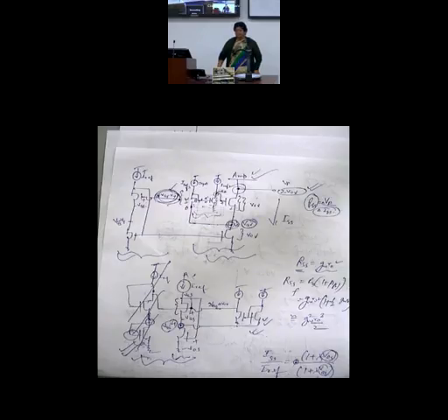So you should learn about small signal modeling, analysis, calculation of small signal parameters, gm, ro, Rin, Rout, the gain, the high frequency behavior, parasitic capacitances, and the different configurations that you have been taught: amplifiers, differential pair, cascode, folded cascode, common gate, common drain, differential pair characteristics. All these things you should at least have a practice.